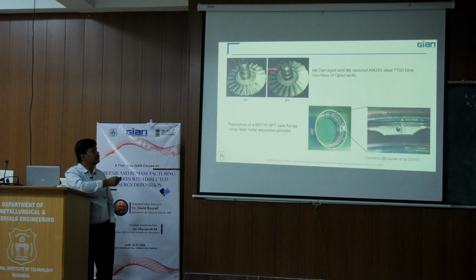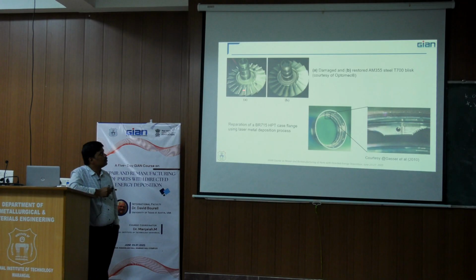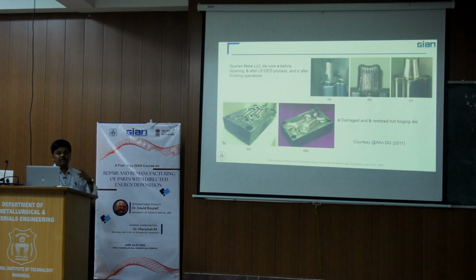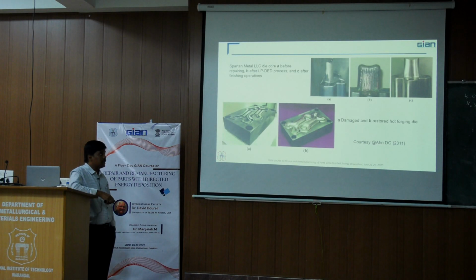Another blisk, if you see here, is one blisk which is worn, and that we can also repair. And if you see, another part is the case flange. The flange can also be added with additional features. And if you want to make multi-material mold dies also. If you see, this is another case study with the laser powder DED process.